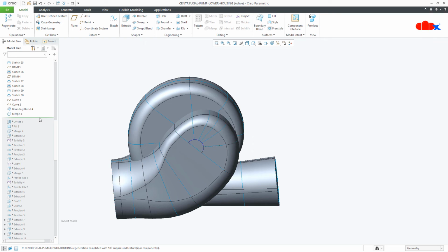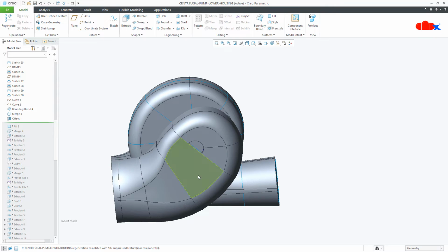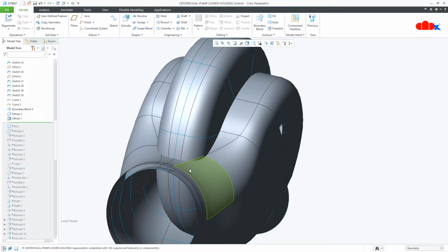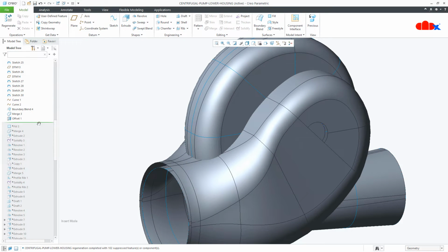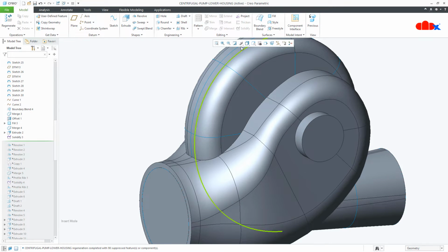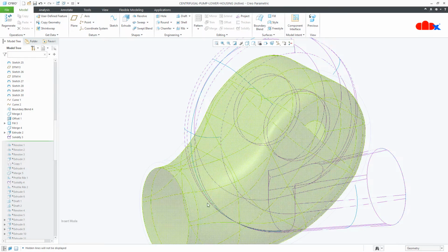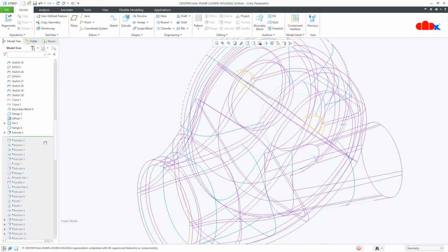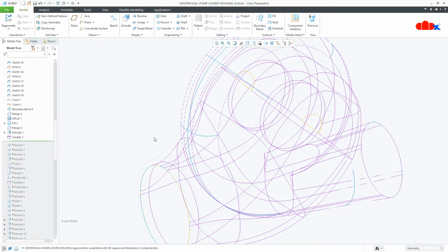Merged. Then this merged surface is offset outside with the required thickness. So this thickness is 20 mm. Then fill surface, merge, extrude to close this area, and then solidify. So once it is solidified, the outer surface will become solid. Now these pink lines are for inner surface.